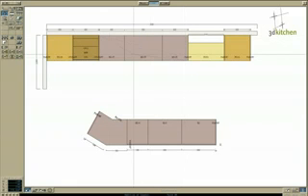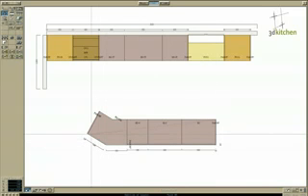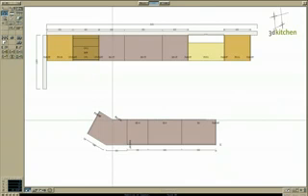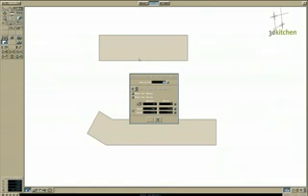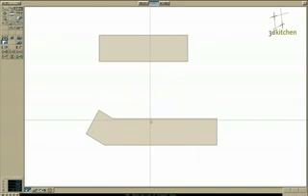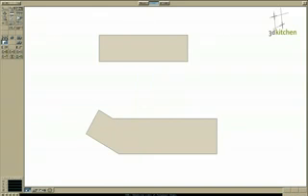Now we're going to place on the benches, so we're moving around the units, dropping the benches into place. Placing one on the island unit now. It's more complex, but it simply snaps into position at the points where the base units change direction. We generate an overhang for those. Specify how far we want to overhang it. So okay to that.